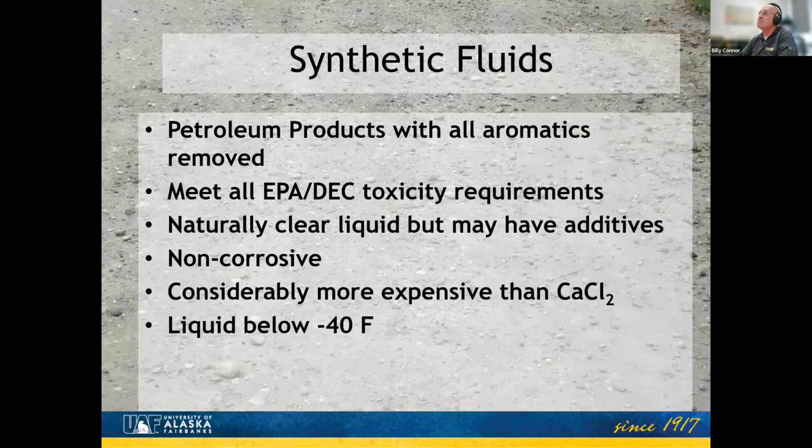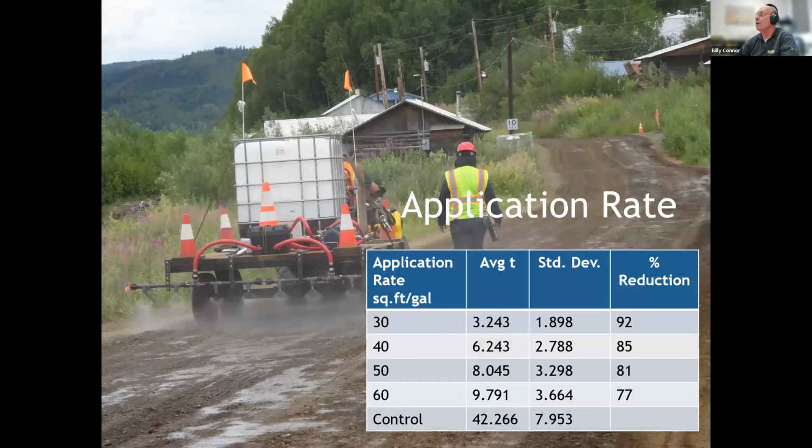So synthetic fluids are petroleum products with all the aromatics removed. They meet all of the EPA, DEC toxicity requirements. They also meet all of the aviation requirements, so that it does not harm aircraft. It's naturally clear, but you may have some additives such as tall oil put in there. Non-corrosive, that's one of the things. It's going to cost you about twice as much as calcium chloride, but it also has some of the other advantages that we noted, and it's liquid down to -40.